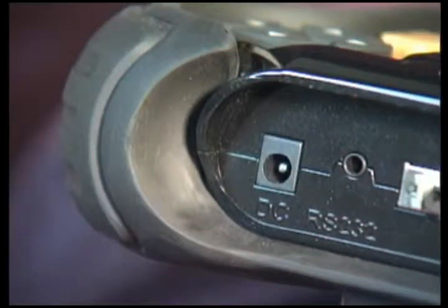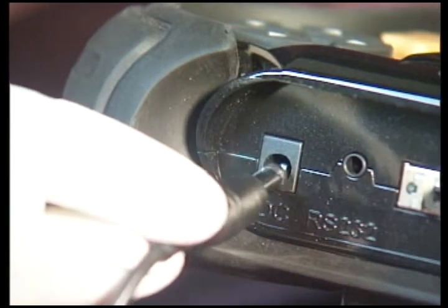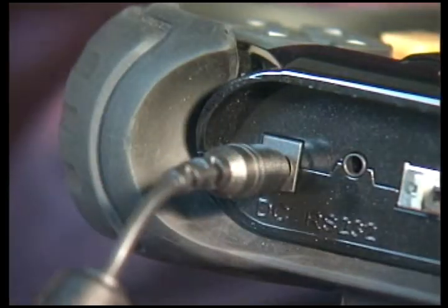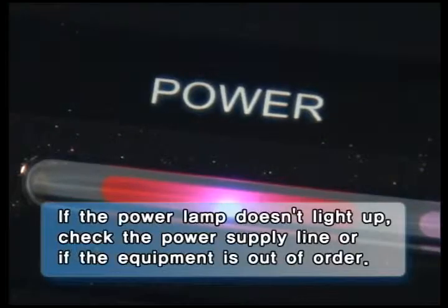There are a total of 5 ways of supplying the power. When the device is powered up, the LED power lamp will light up in red. If it doesn't power up, please check the power supply line and check for device defects.